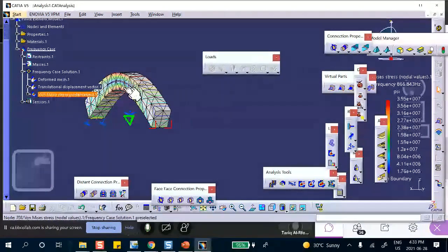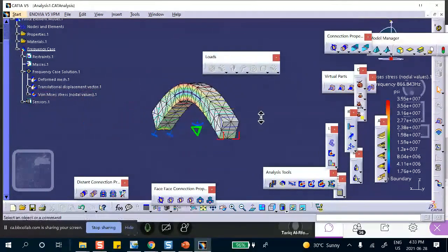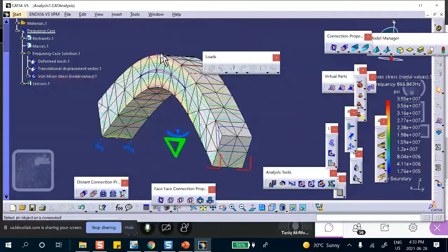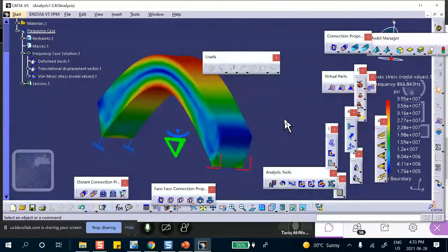So it tells you, if it vibrated at that mode, where the biggest stress is going to be, but you don't have to be a brain surgeon to know that, because you know that a simply supported beam has the biggest stress at the middle point. You don't have to be a second-year student to know that. But these numbers are totally garbage, useless. The frequency is not, but these numbers are, because displacements are total garbage.